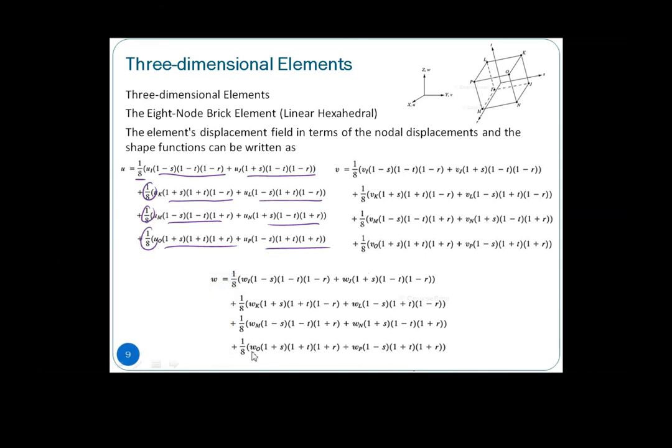For two-dimensional and onwards, we can make use of these shape functions to determine, let's say, the temperature, displacement, and also stresses at a point that is not at the nodes, that is, not at the nodal parameters or variables themselves.